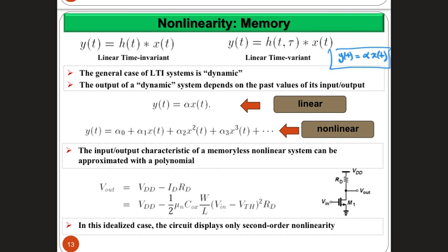But generally speaking, it's going to look like the output at time t is dependent on the input only at time t. In general, and I hope you still remember that from your signals and systems course, most of the systems that we deal with, even the linear time invariant systems, most of them are with memory, right? The only exceptional case is if the impulse response was a single delta. That's the only case where the output of the system is going to be dependent only on the current input of the system. For any general h of t, remember the convolution operation.